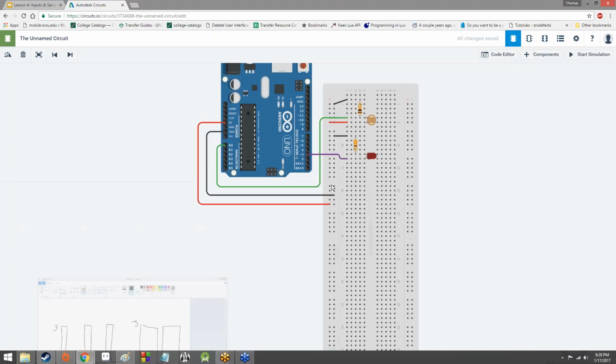Hopefully that made sense. Basically, pulse width modulation is just a fancy term for turning the power on and off really fast and pretending like it's an analog signal. So the Arduino can do that. So we can utilize pulse width modulation on the digital side in order to simulate an analog output. So we can take our analog input and we can send an analog output, sort of,